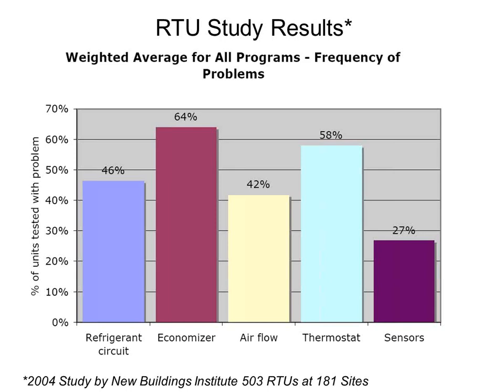Thermostats, 58% of the time, were not optimized correctly. That doesn't necessarily mean they were failed, but it could mean that no one had a schedule in there whatsoever, or they had set points that were not very useful, or they had a schedule with no set points, or they had heating and cooling running simultaneously, just a collection of things like that. But most of the time, it was not being scheduled.